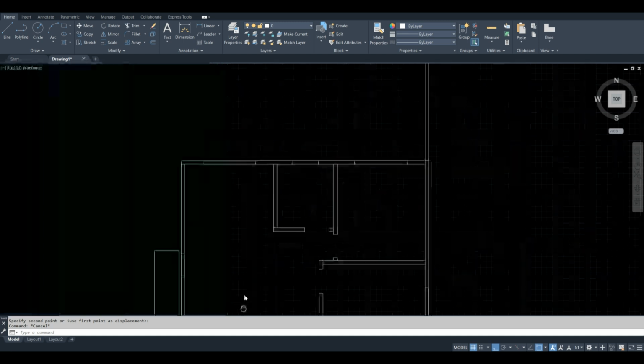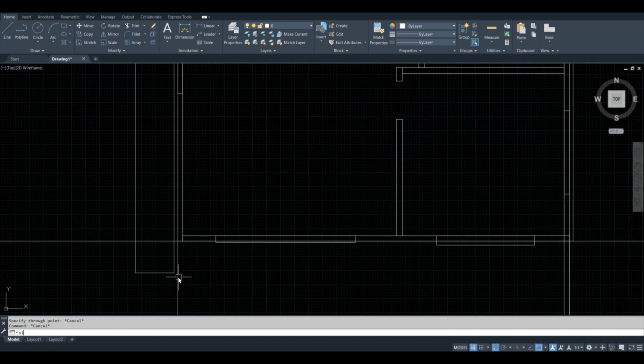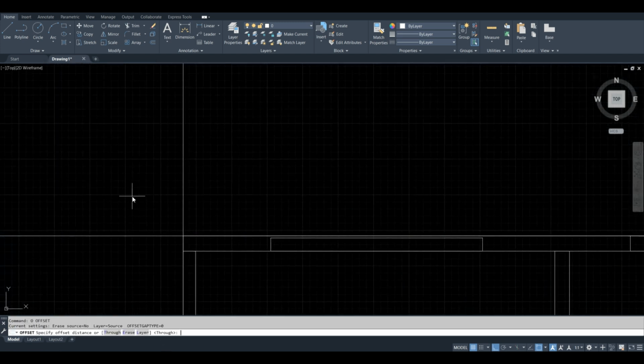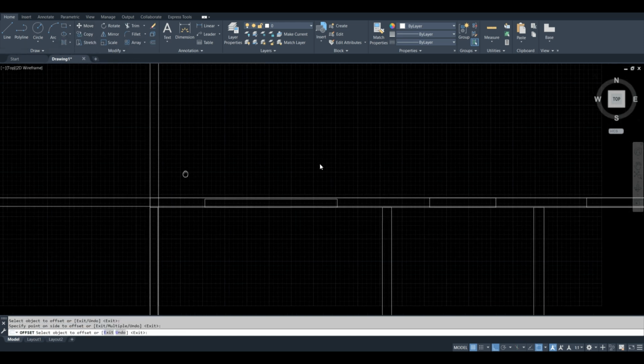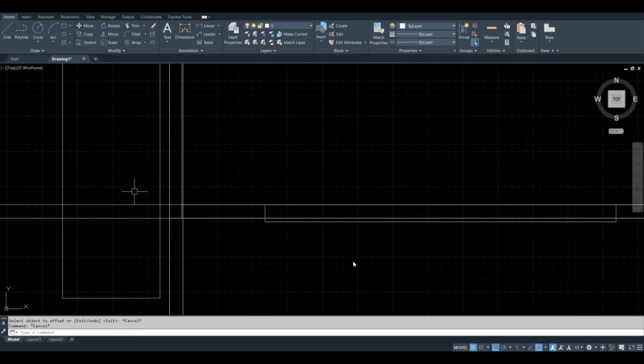Fixing gaps and overlapping corners in AutoCAD, walls, and windows. Once you've moved the image and are reviewing your tracing, check carefully for any gaps between wall lines, walls that don't meet exactly at corners, overlapping lines at window or door openings. Here's how to fix them.